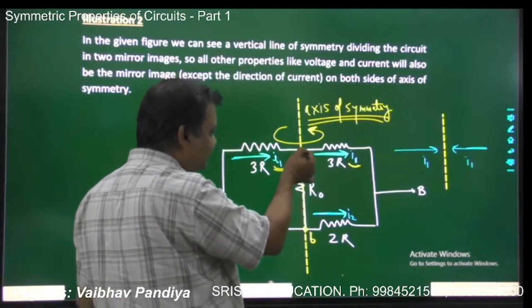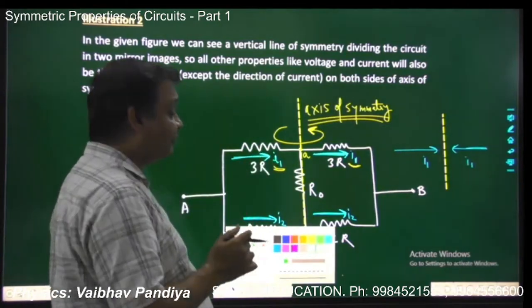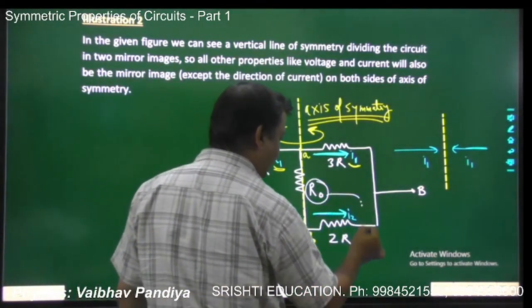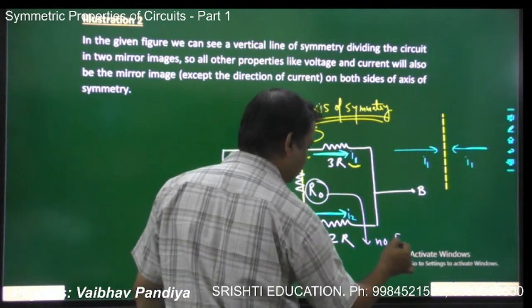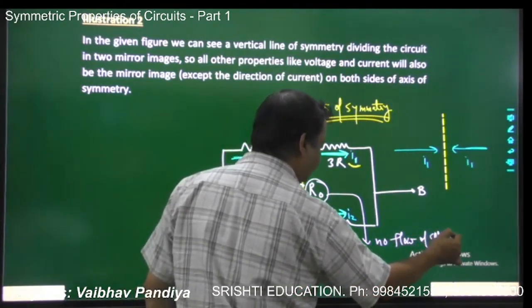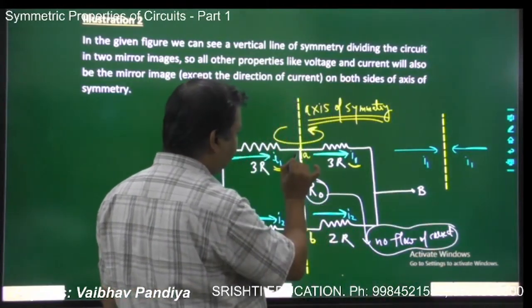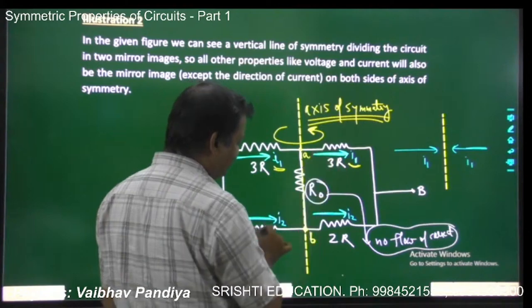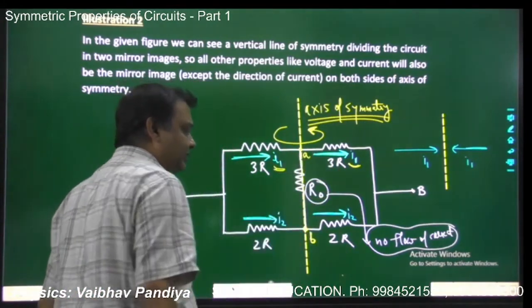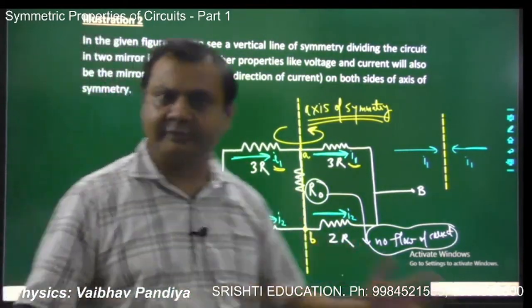And since no current is dividing at A and no current is dividing at B, on the argument of symmetry, what can you judge? You can judge that R naught will have no flow of current, correct? Because no current is getting divided at A, no current is dividing at B, whole I1 is coming and whole I1 is leaving at A, and the same thing goes for I2. So R naught will be a passive element in this circuit. There is no current in R naught. So many things can be concluded by the concept of symmetry, okay?